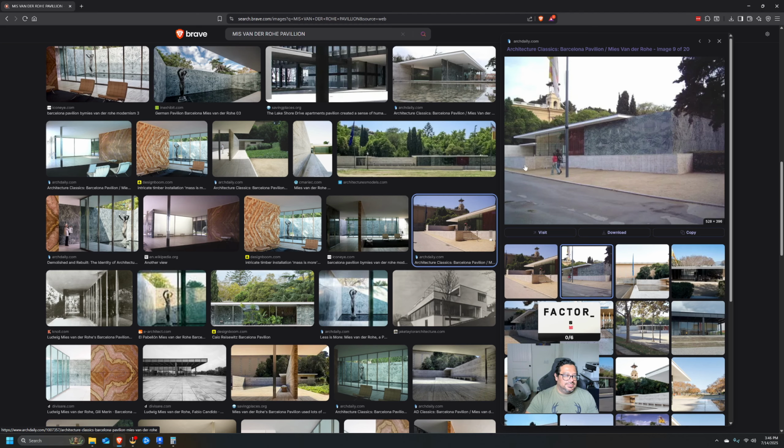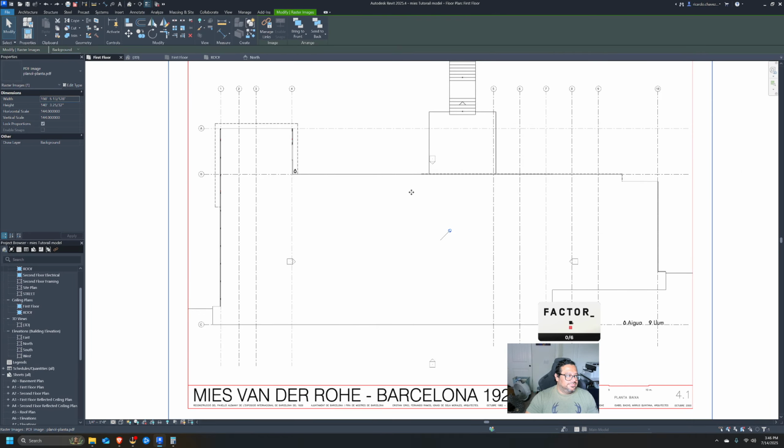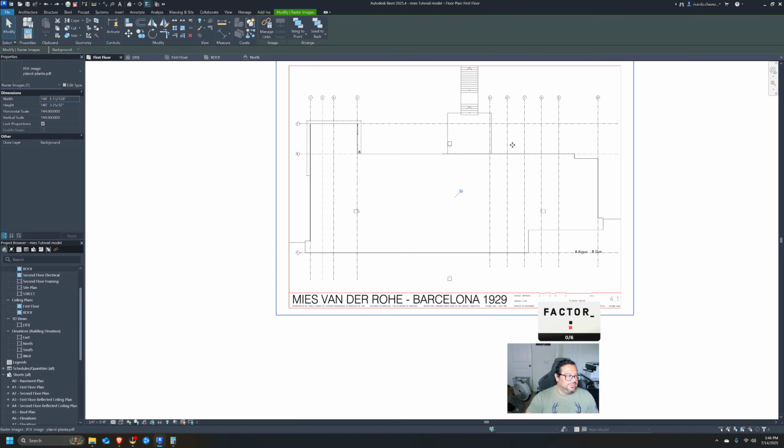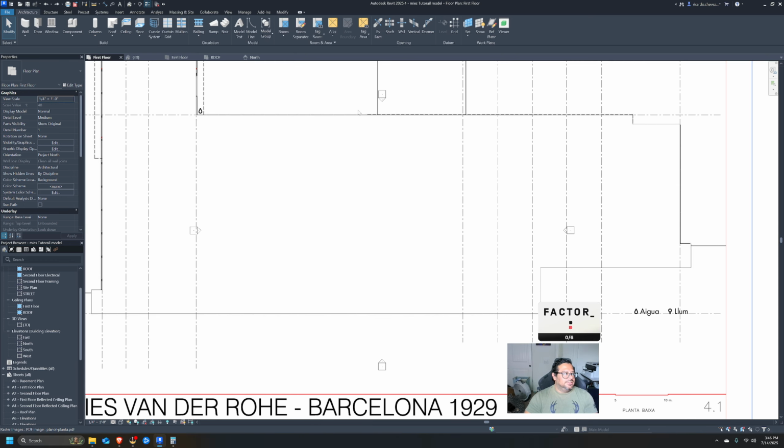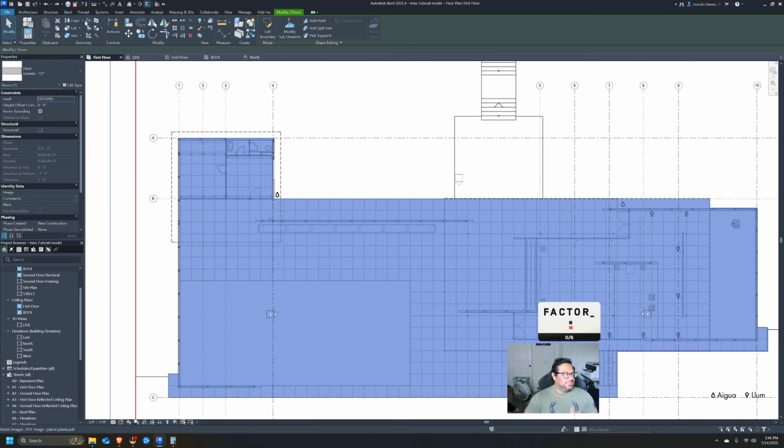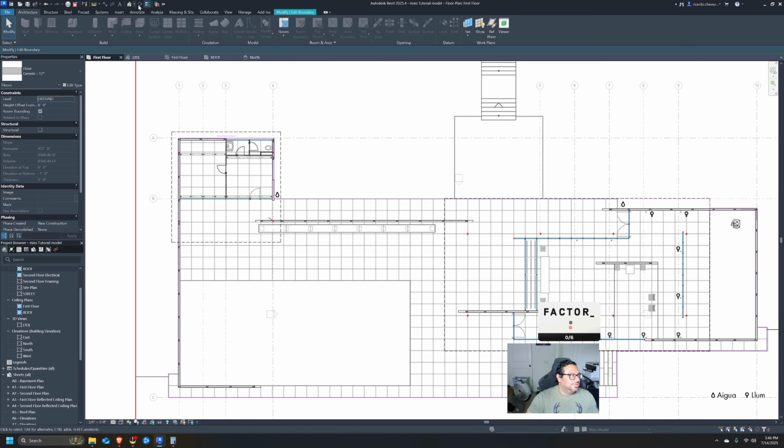To do that, we're going to create a new floor type. So that's a good time to talk about it. We know we're going to drop down 4 feet 6. So that's our floor. We did that online, right? If you want to know how we did it, you click on floor here, and then we basically drew it. Let me delete it.